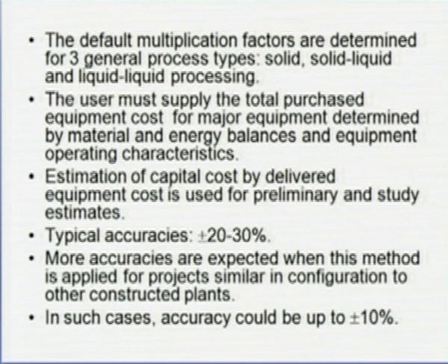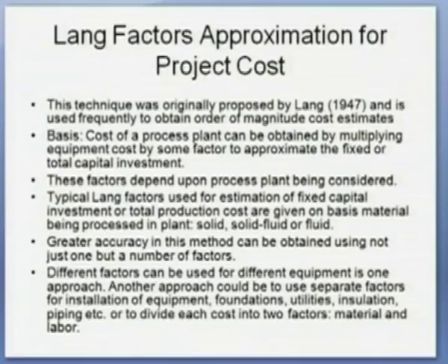Okay, the typical Lang factors that are used for estimation of fixed capital investment or the total production cost are given on the basis of material being processed in the plant, whether it is a solid, solid fluid, or completely fluid material. Greater accuracy in this method can be obtained by using not just one but a number of factors. Different factors can be used for different equipment. That is one approach, and another approach could be to use separate factors for installation of equipment, then for foundation, utilities, insulation, piping, etc. So, multiple factors,